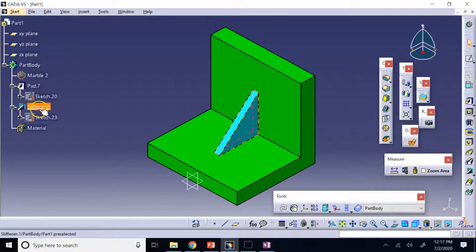Let's say this is a stiffener for a moment. I say, well, what if this stiffener is not there? What happens? Should I delete it to see, or I can just deactivate it temporarily? Yes, it's always a good idea to deactivate. So if you decide to put it back, you don't have to recreate it, because once you delete it, it's gone.